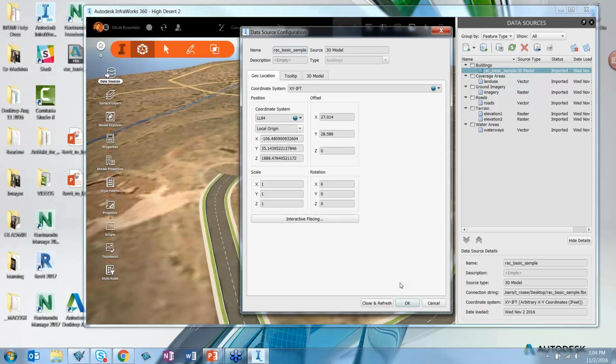But the problem is the Revit models, typically those project base points, it's somewhere on the model, which is your 0, 0. Whereas with InfraWorks and just like Civil 3D, it's a coordinate system, and there are many coordinate systems for every area that you live in, and they're in thousands or millions of units compared to the 0. So there's a little bit of change that has to be made there to get those to line up. But it's a work in progress. We're hoping for future better. We'll see. Yeah, it's definitely something that is being worked on.